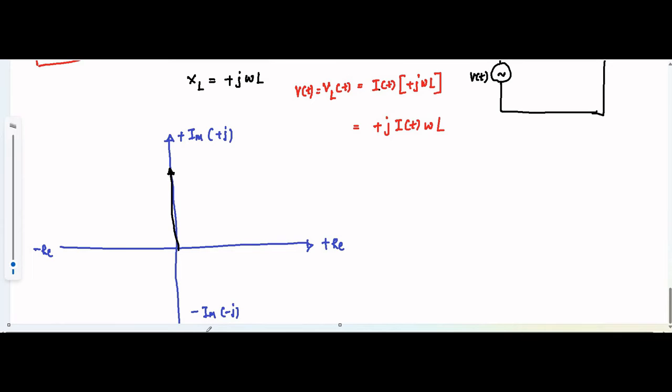And VLT and IT, if we take that, it has no imaginary part and it is positive. So this is IT, this is Vt. So voltage leads current by pi by 2 radian or 90 degrees, or current lags behind the voltage by pi by 2 radian or 90 degrees. So if you go by the complex number approach as well, with positive and negative, real and imaginary axes, you will get the same result.